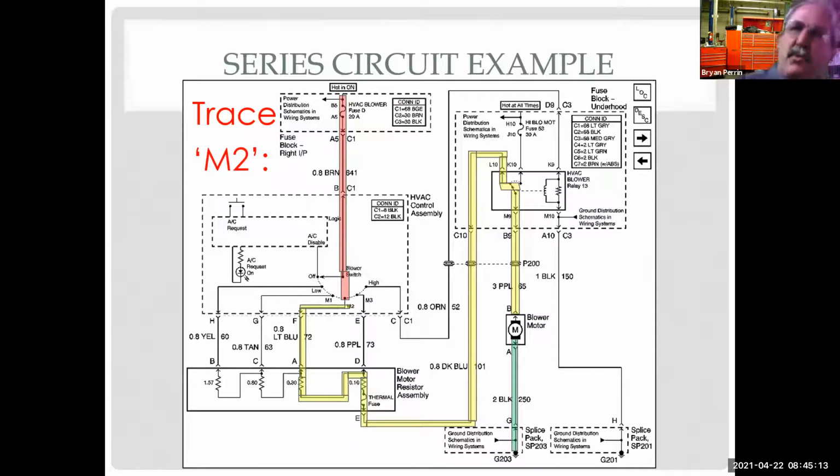It's just a continuation of the voltage drop exercises we did yesterday, but now I'm putting it into a circuit. Yesterday on Tuesday, we were saying we're not dropping voltage because the switch is open, or we're dropping all of our voltage across the switch where we have potential on either side. And here, all we're doing is seeing that potential.